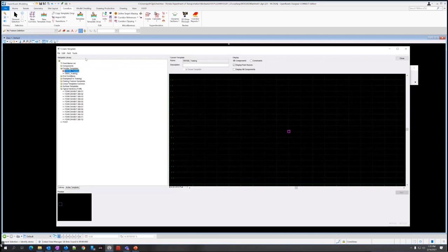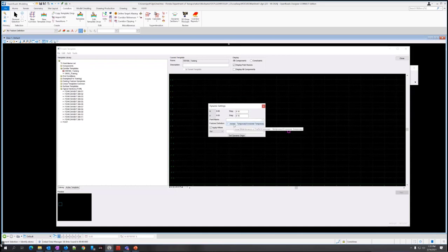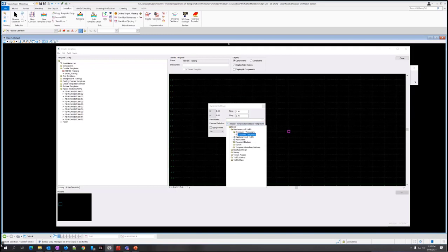So we're looking for the Tools menu again. We're going to Dynamic Settings, the last one on the menu. Here we want to change this feature definition to template miscellaneous. Most of the feature definitions, it only picked this crossover temporary because it's just the first one in the list of all our feature definitions. But for template design, most of what you're going to need is under template points. Make sure it matches our QC.